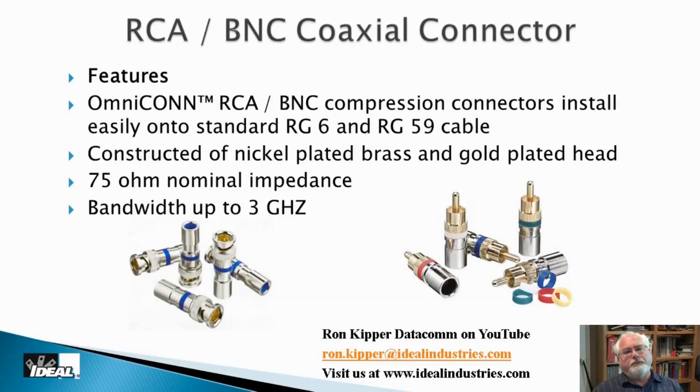The other connector out there is called an RCA. In the audio-video world, we use a lot of RCA connectors, which are named after that famous little company who in the 40s or whatever it was developed those phonographs, and we would use the speakers in existing stereos, so they developed that little connector. Now, both the RCA and the BNCs have pins in them, and so that's the center pin on an RCA. There's a little bit of pin inside of a BNC as well. F connectors are considered pinless. The center conductor actually is the pin. We used to solder or crimp pins on those connectors, and you'll find that they're typically compression today, and we no longer have to do that. But those are two other connectors you'll run across when dealing with coax.